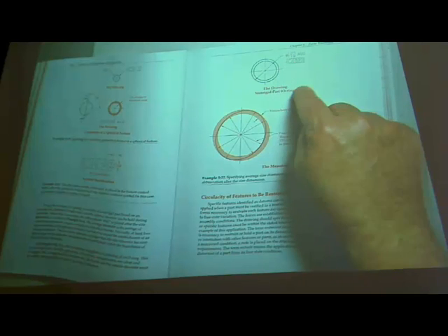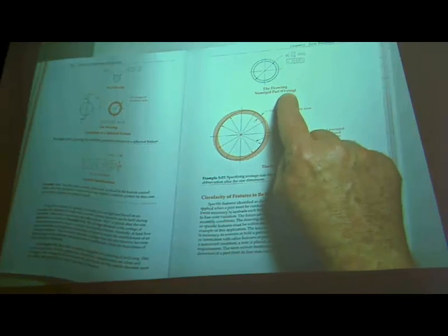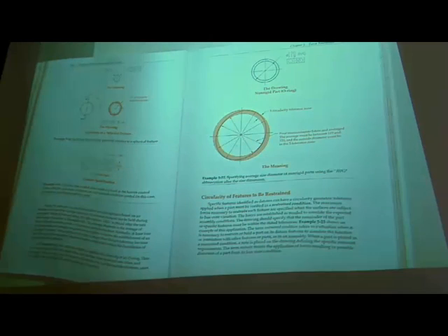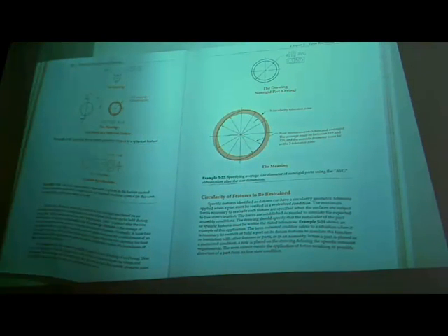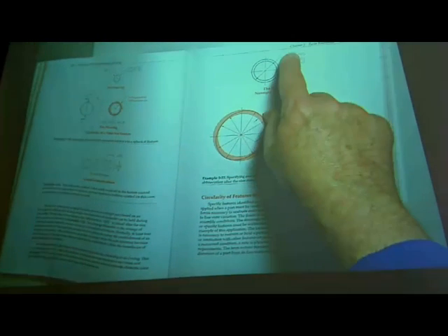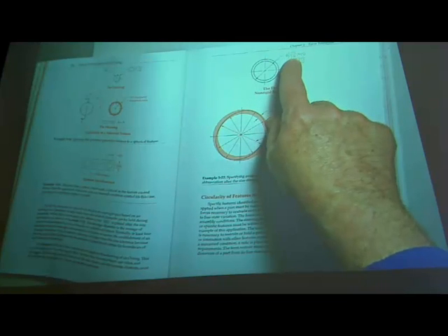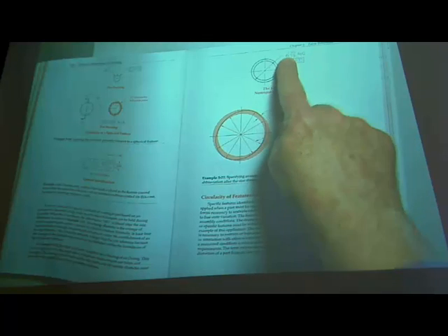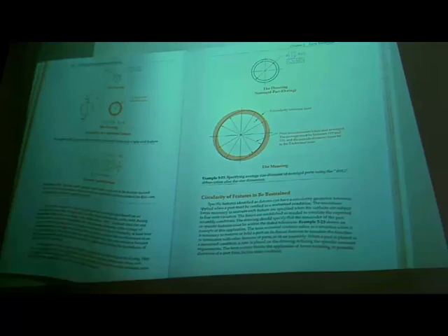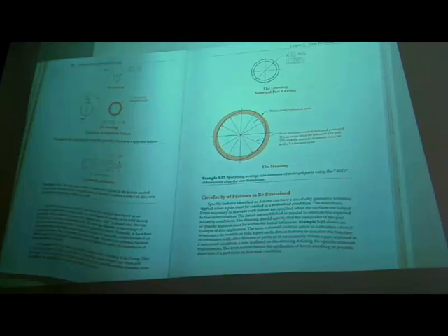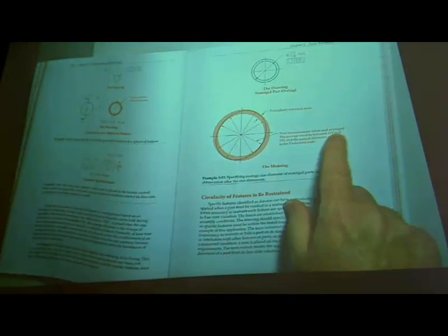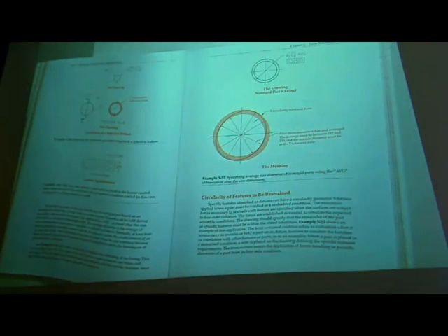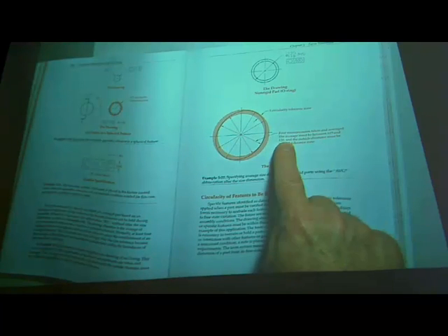We'll create a drawing, for instance, for an O-ring, and because of this flexibility and non-rigid state, we'll provide a kind of limit tolerance, but it's an average that might be measured in four or five places, at least four places. Okay, four measurements taken and averaged must be between this range.